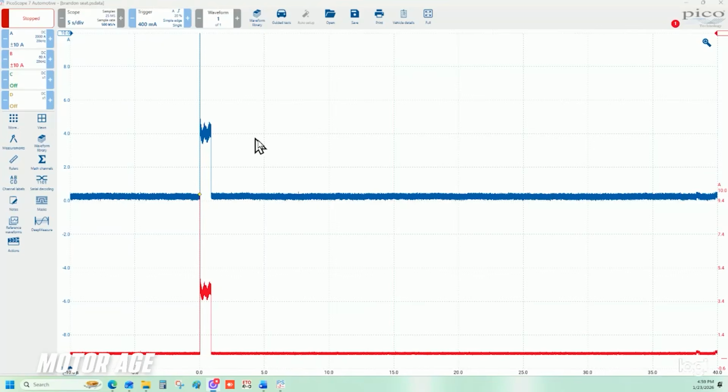Reviewing our capture, we're showing, of course, current flow leaving the battery in blue and simultaneously current flow leaving fuse box A in red. And of course, they line up, proving that not only do we have a draw, but the draw is in fact of the wire that we are referencing at the time, that black wire leaving SA4 of the underhood fuse box. Now, there's some clues to be yielded here. Of course, I created this fault, but let's pretend I didn't, just for several minutes, to prove a point.